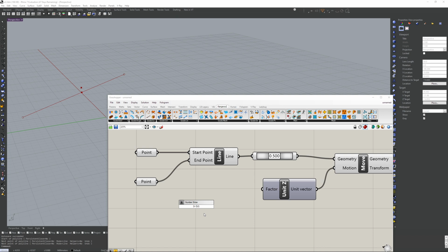If we wanted to create finer control and have more decimal points in between, you just add more decimal points. However many you add here is how fine your number slider will be. Ours right now has 3 decimal points. So we just connect that to it.